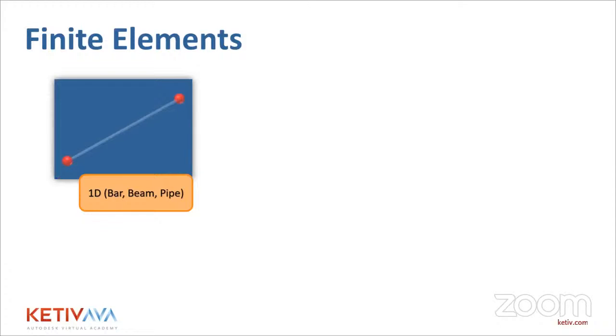Now, to define the geometry or cross-section for a beam element is going to require several cross-sectional properties. To input this data, you can either put that in from empirical data, or what's recommended is that you use the inbuilt element library, which has a lot of preset standard sizes that you can just pick, and it's going to populate every property that you need for you.